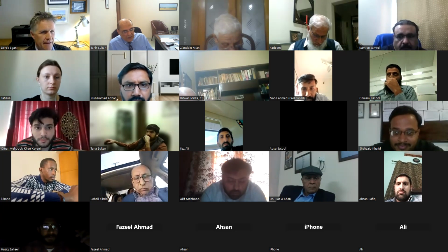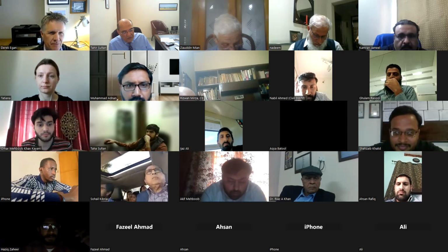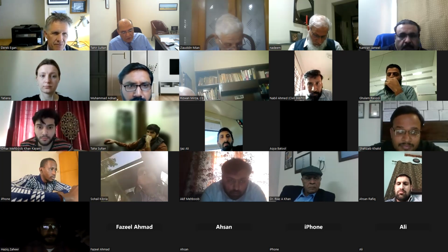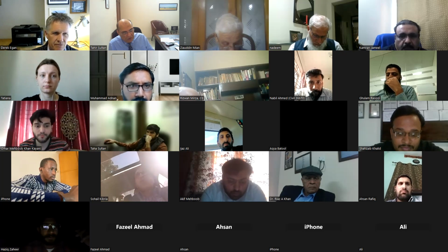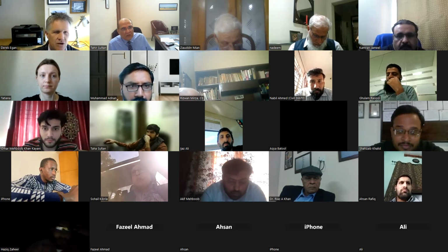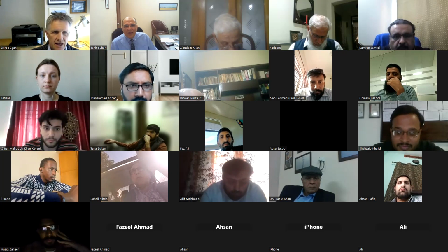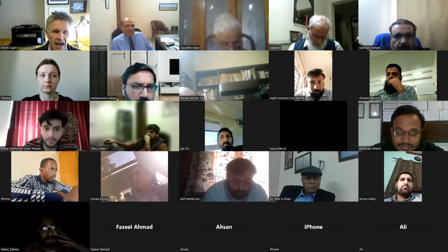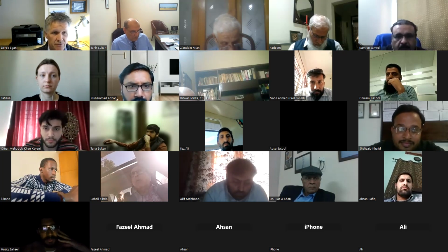Haziq Zahir is asking, do we not even provide minimum reinforcement in the rigid inclusions column, unlike piles? I think reinforcement is not required at all. Yeah, they can be completely unreinforced.